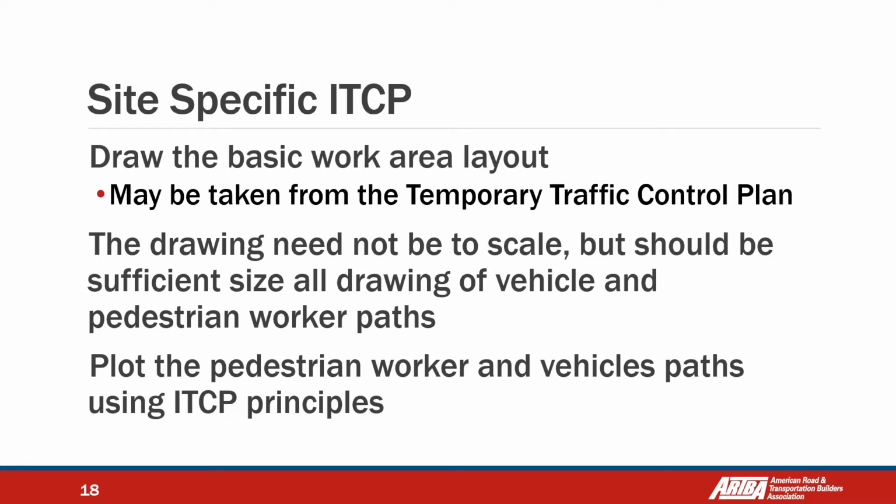Draw the basic work area layout, maybe taken from the temporary traffic control plan. The activity zone is inside the temporary traffic control plan, but we are focusing on the activity zone and the traffic inside of the work zone, not outside of it. But the temporary traffic control plan can give us a perspective about the location and circumstances of our project. The drawing need not be to scale, but should be of sufficient size, showing all vehicle and pedestrian worker paths. Plot the pedestrian worker and vehicle paths using internal traffic control plan principles.